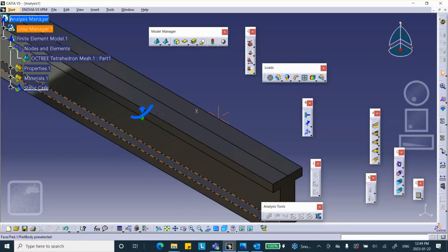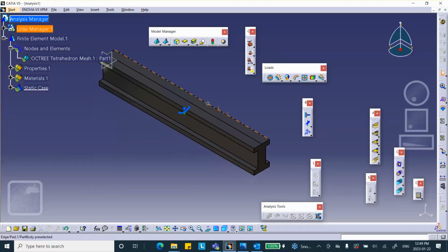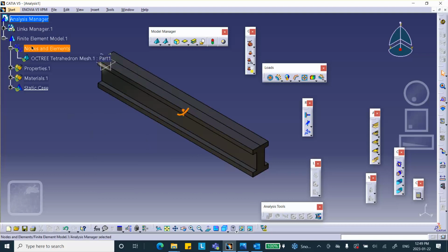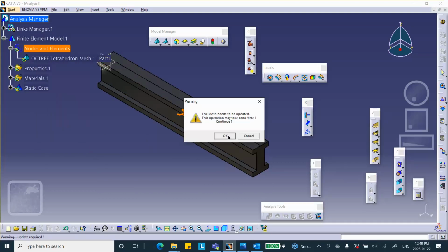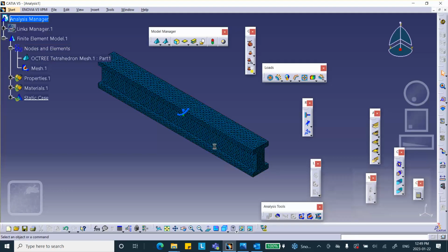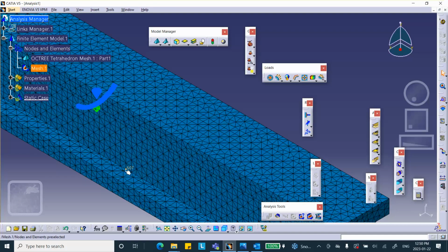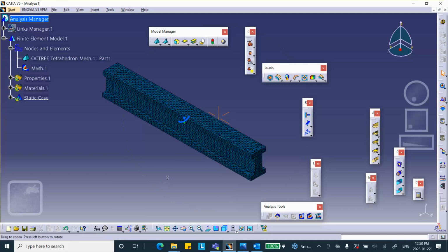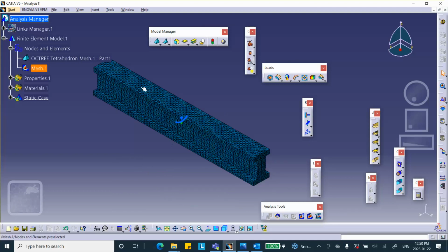Well, at least we're going to kill the fly with a cannon, so that's okay. Right click, mesh visualization. It's going to be a lot of unnecessary elements, but hey, it's free. We're not paying for it. Okay. But if you're working for a company, these things actually have implications. Big elements: fast, cheap, inaccurate. Small elements: slow, more accurate. But making elements small everywhere does not make sense.